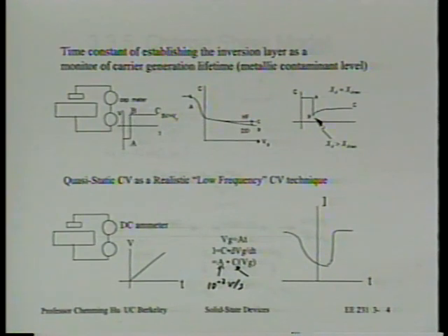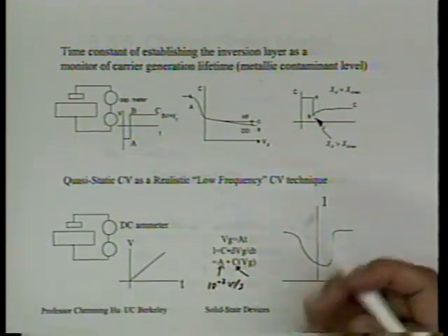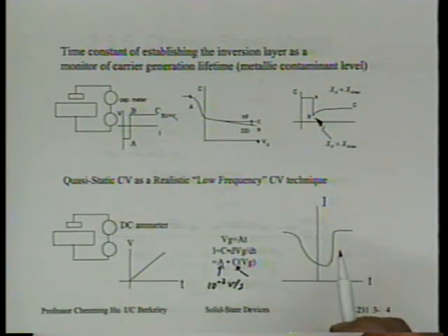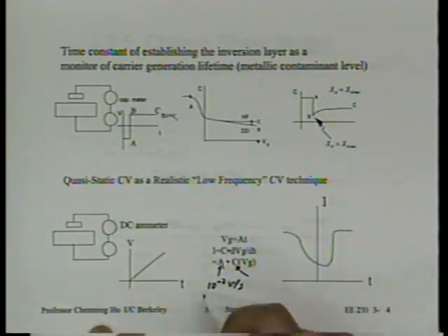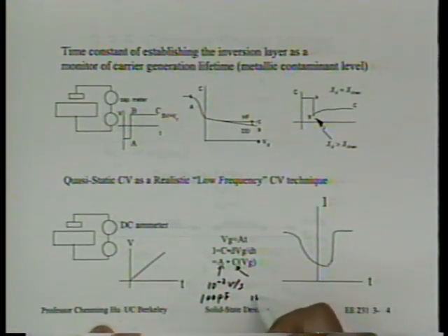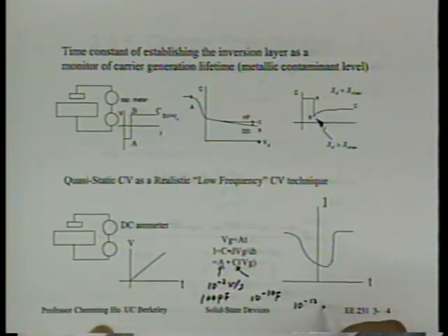Picofarad, right? We usually get several tens of picofarad with no problem, right? Okay, so let's call this 100 picofarad. Let's see what current we get, all right? So, suppose it's 100 picofarad. That is 10 to the minus 10 farad times 10 to the minus 2 volt per second, which is 10 to the minus 12 ampere.